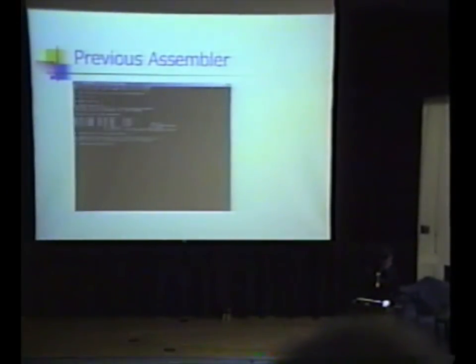As you can see in the previous assembler, you have to know some DOS code to find the directory, and you have to know the code to run the assembler, which is just ASM51, then the file name -if.